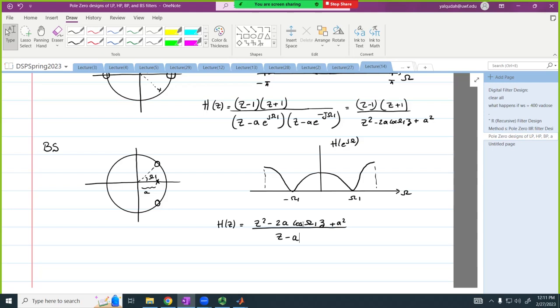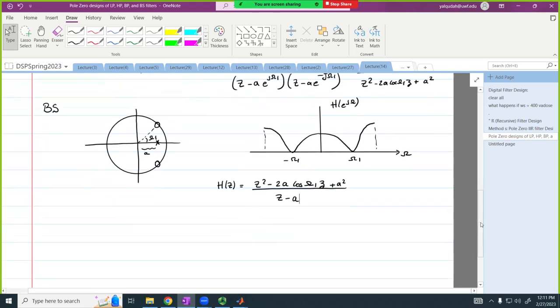So for this to be an IIR filter, I have to have a pole. Because when I multiply by y, I'm going to get a y that depends on another y. Does that make sense? If there was no denominator, y over x, then y only depends on the input. It becomes an FIR filter. Okay, very good question.